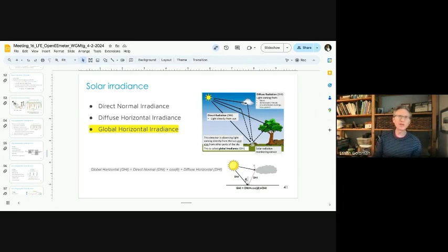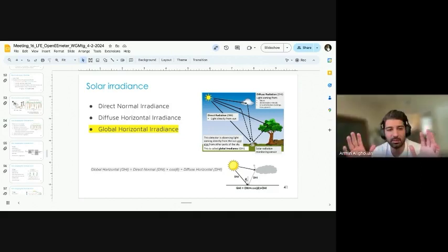But it sounds like we haven't gone to a balance point and degree day model, but temperature obviously has a relationship. Does temperature have a different linear relationship essentially for each hour of the year effectively? It depends on the meter itself. It's purely data driven, and we let the model and the training or the optimization decide what the relationship is for each meter. So we're not bounding it by the balance point. We don't even have that in our definition at all.